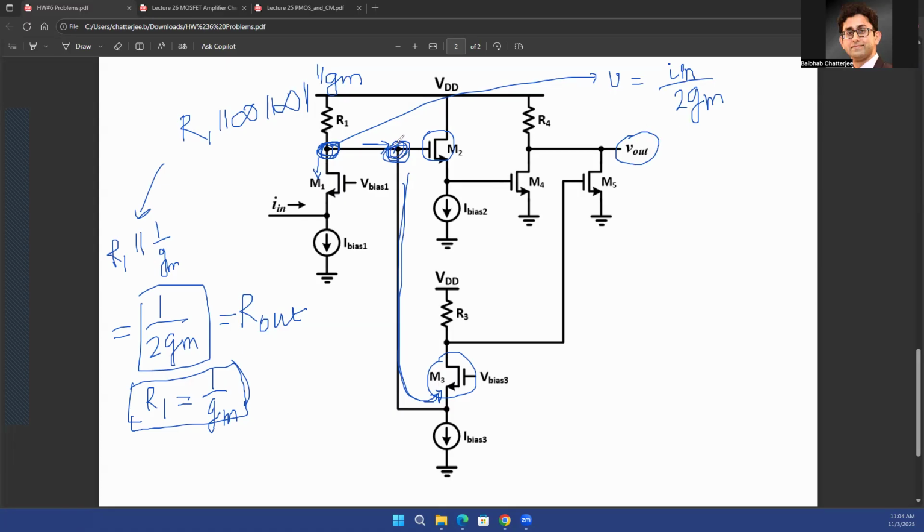So, are we doing that weird thing with V out? Because gain usually is V out, V in, or I out, I in. So gain can be, if it is voltage gain, V out over V in. If it is current gain, it's I out over I in. If it is transimpedance gain, it's V out over I in. And if it is transconductance gain, it's I out over V in. So gain can be any of these four, right?